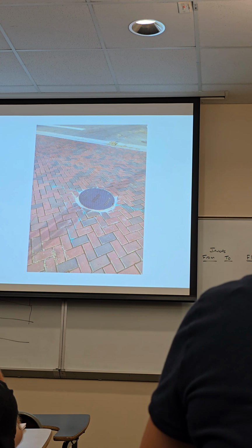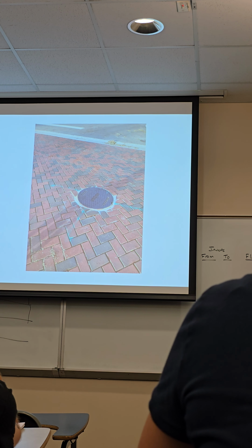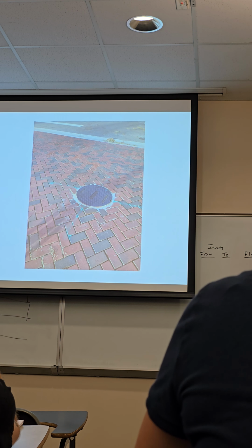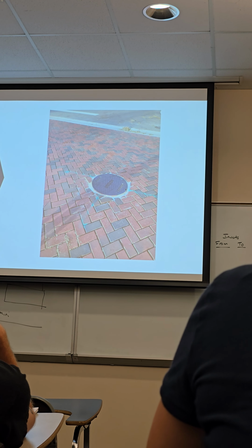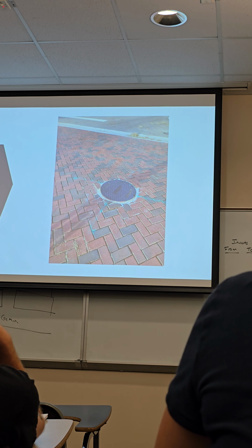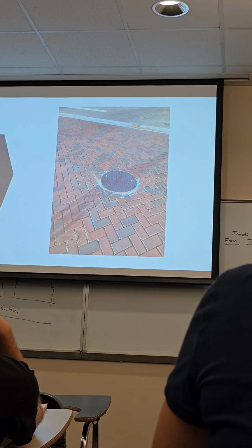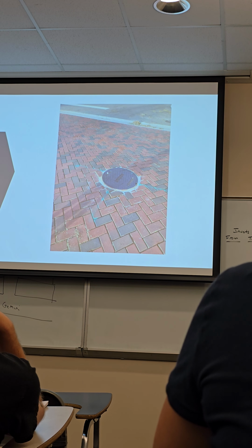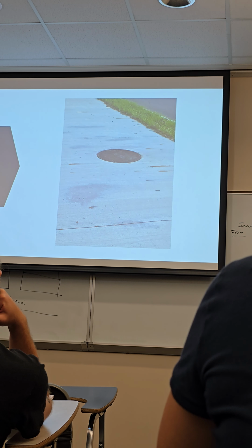What happens over time is those brick pavers settle, and then that manhole ends up having a lip on it, and people hit it with their car. So it's really tough to get this right. I saw this and thought, man, that's crazy, but this is a pretty new installation and it's already settling, so it's kind of a pain. But a very, very common situation.